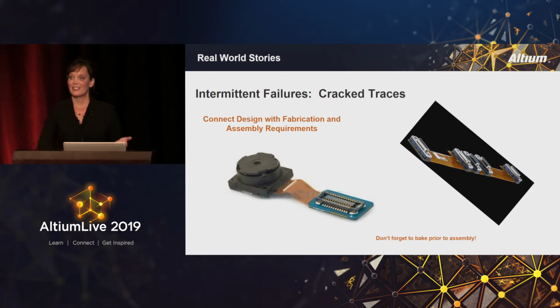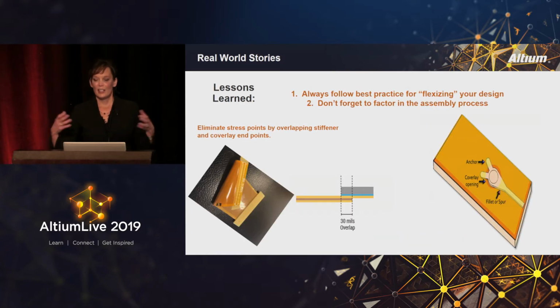They cross-sectioned the component area that was cracking and made a first recommendation to go from 1 mil Kapton to 2 mil Kapton in the base laminate to give it a little more stability. But more importantly, they realized that for whatever reason, that component area wasn't flex-sized, as we would call it, where you're going to want to add nice fillets and teardrops to the pad and trace interface.